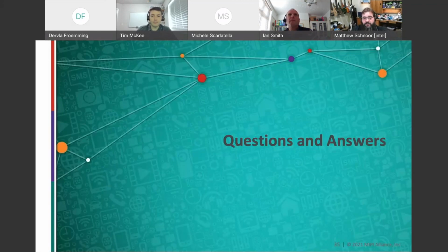And that's an advantage over some of the other defined reset methods in I2C or SMBus, which just hold both the lines low for a long period of time, and then every device is supposed to assume a reset is required in that part. RSTACT and the target reset pattern offer much better and more fine-grained control than those methods.